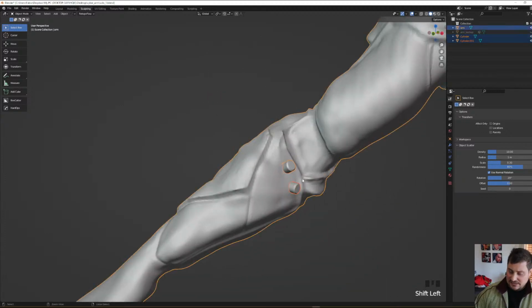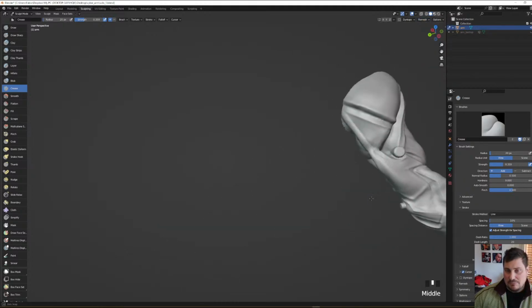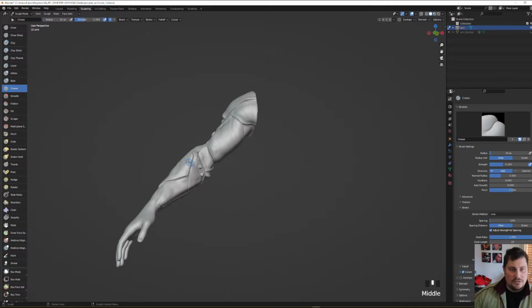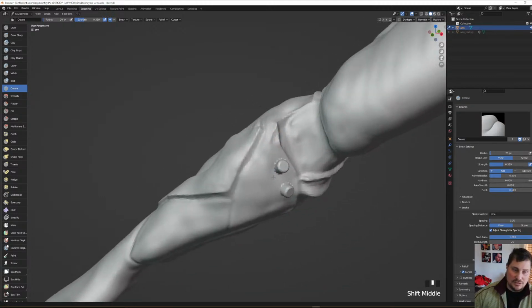Then I select this element, Control J, go back into sculpt mode. I can leave the different sets and then do a remesh so that these become part of the geometry. So as you can see, I'm adding a lot more details to the initial design.